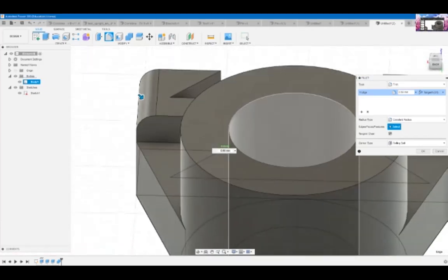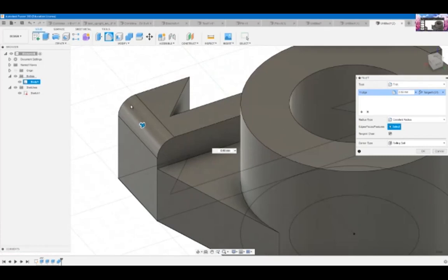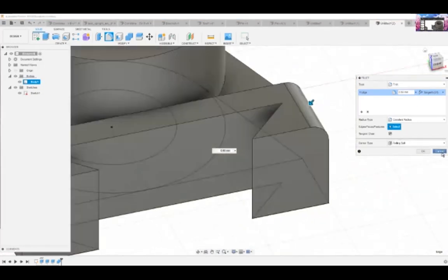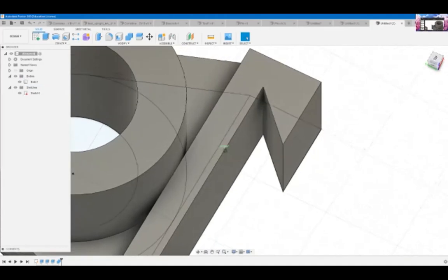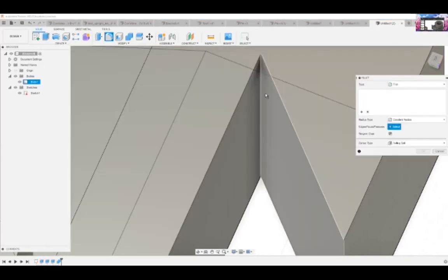You'll be seeing these a lot in a lot of other parts we make. Fillets are generally multi-purpose, either to make the part look nicer, or because, in the context of, say, what's a better example here? I was wanting to use that corner. I can use the dovetail because that helps illustrate my point a bit more. So if you can see here in the dovetail, this vertex is a very, very sharp vertex, which, as you learn in Mech 363, sharp corners in general are no good, because those are stress concentrations. That's where fillets come in.